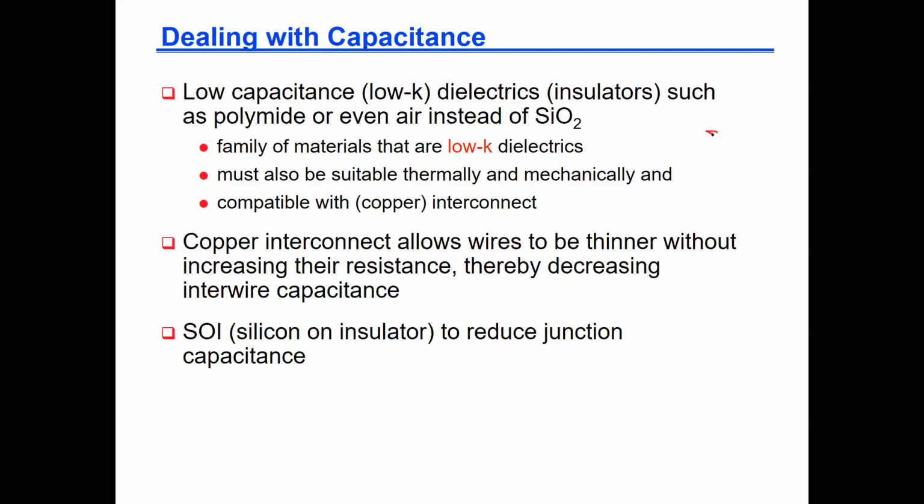Since the capacitance is epsilon A over D, and epsilon is what matters for us, it is the coefficient that shows up in those tables. They try to go for low-K dielectric. If you remember when we did the transistor, the transistor current is proportional to Cox. So for the transistor current I want to increase my Cox so the current increases. That is why we did the high-K homework example.